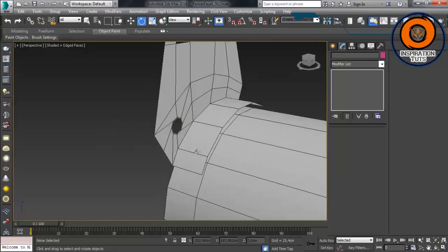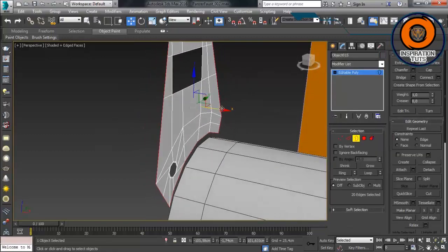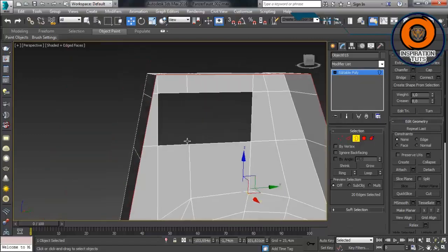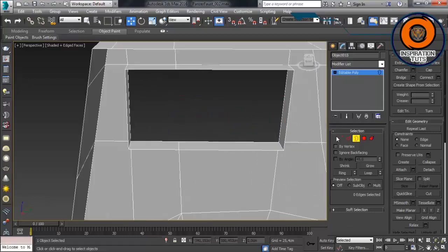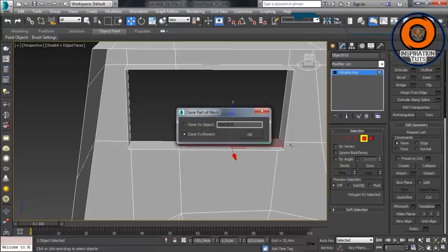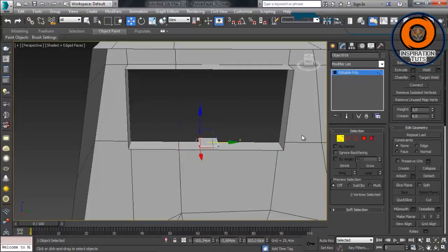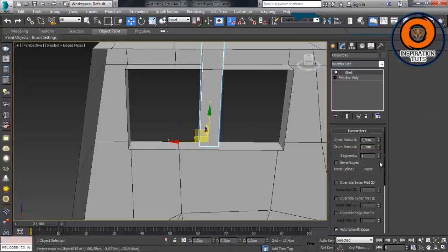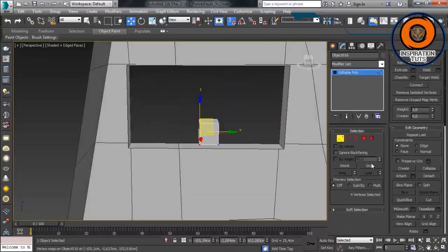Okay, insert once again just to hold the structure of this circle of selection, because we want it to hold tight. Okay, do the same thing here. Just extrude this area, and maybe we're gonna use this surface as a starting point of creating the pieces, the piece that we're gonna use in the front side, of course.